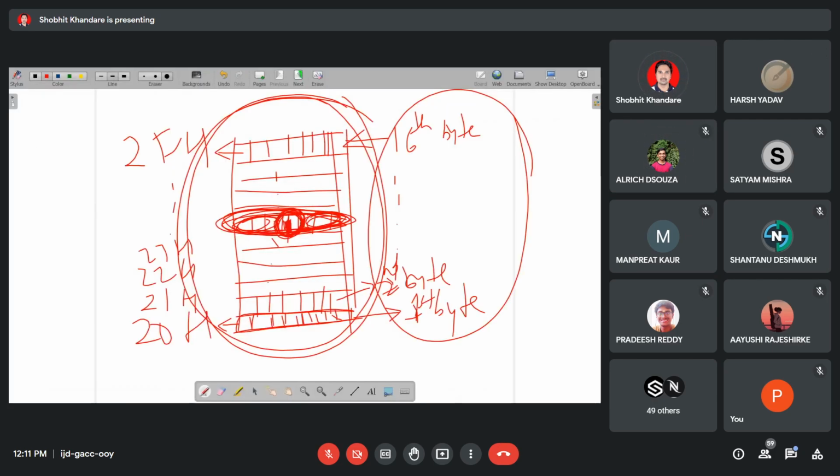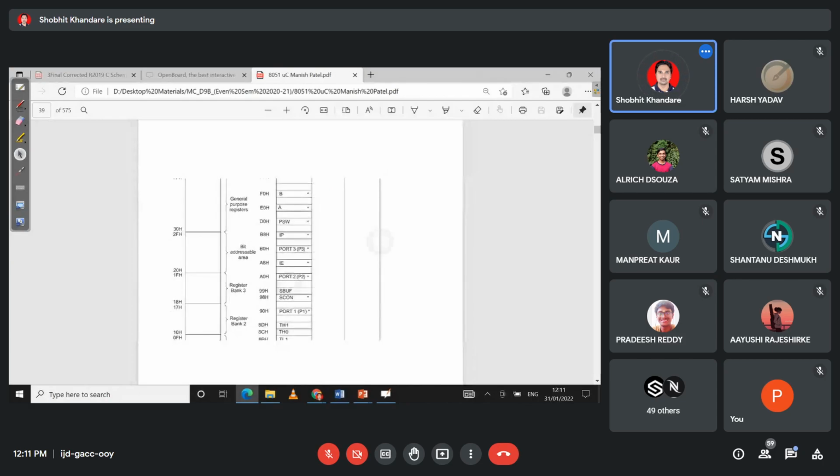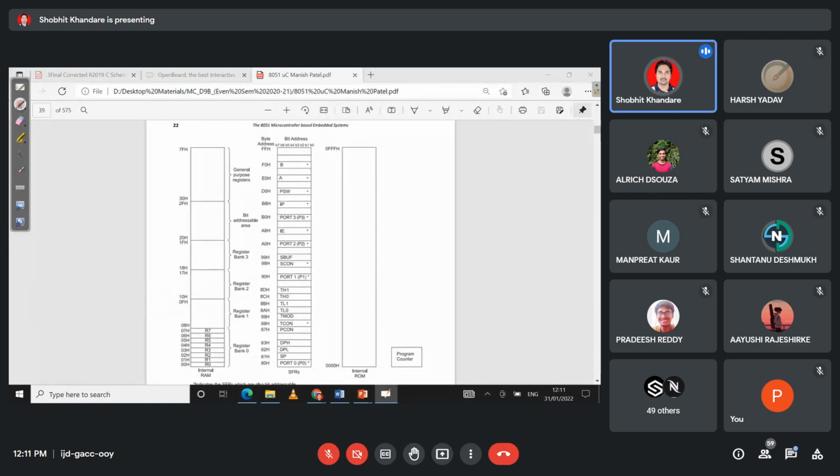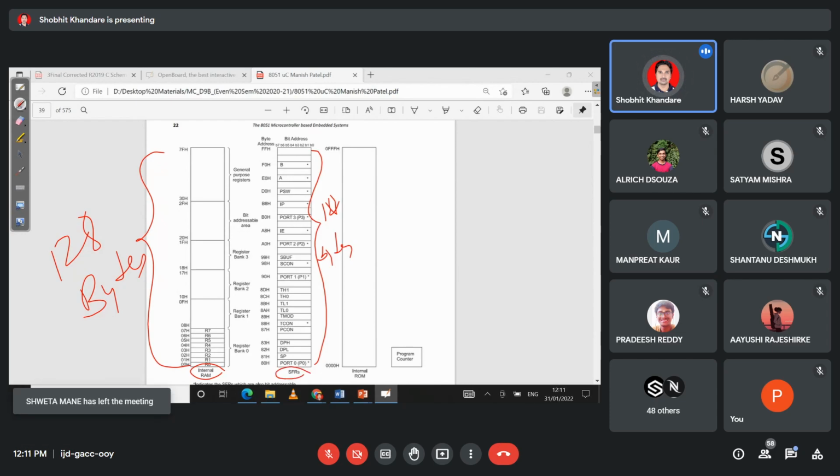Yes, sir. Okay, good. So अभी I was explaining you SFR. तो मैंने आपको इंटरनल रैम पढ़ाया 128 बाइट्स. जो स्पेशल फंक्शन रजिस्टर्स है, ओके, उनका एड्रेस स्टार्टिंग होता है 80H से लेके लास्ट FFH. ओके, तो ये देखो यहाँ पे बिट एड्रेस है और यहाँ पे बाइट एड्रेस है. तो ये सब आपके बाइट एड्रेस है और बिट एड्रेसेबल है. इसका मतलब जहां जहां पे एस्ट्रिक है वही बिट एड्रेसेबल है.